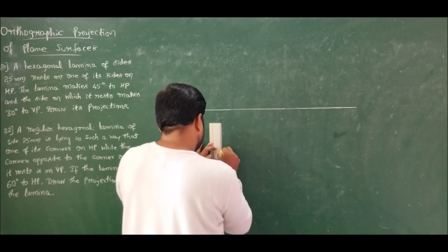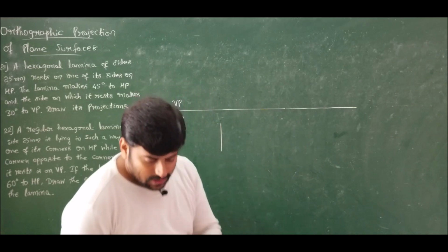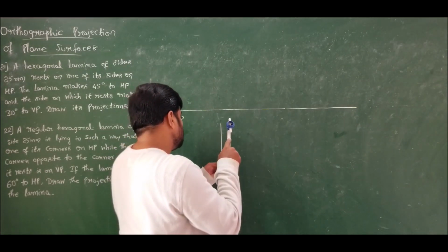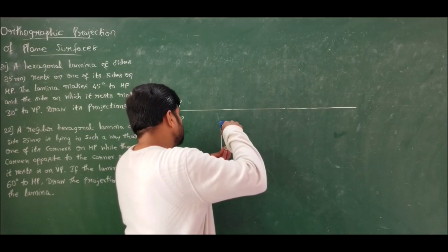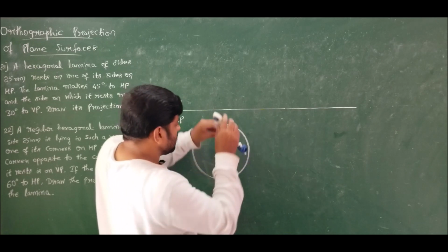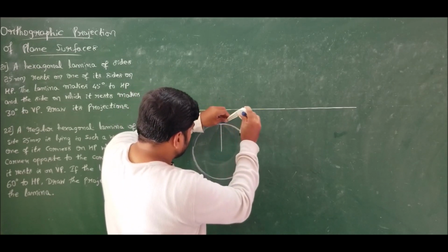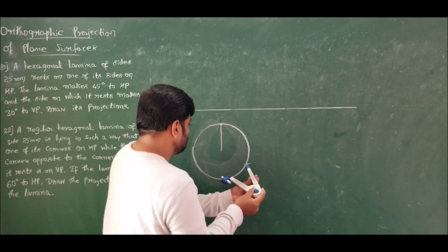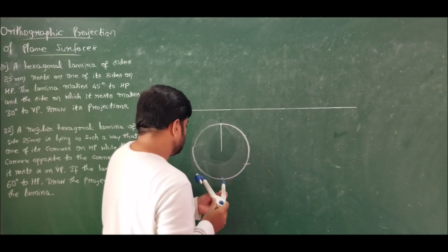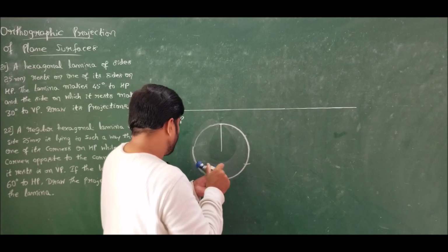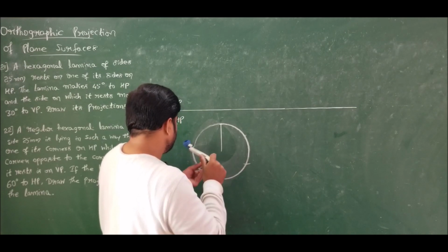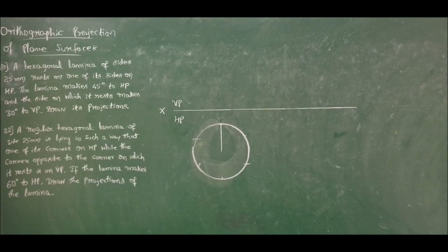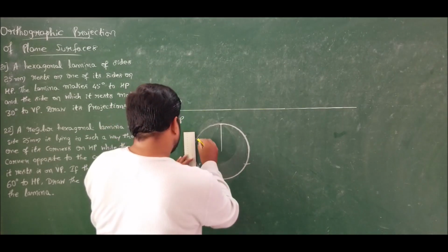Drawn. Next, using this as a radius, construct a circle using compass. Once you construct a circle, cut arcs at equal intervals: 1, 2, 3, 4 and finally 5. Now join these arcs to get the required hexagon of 25 mm sides.